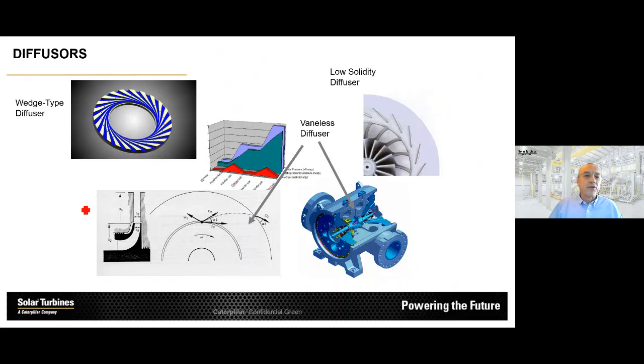After the impeller, and I had mentioned that in my slide, comes the diffuser. And we will talk about the function of that diffuser a bit more. The idea is that in the diffuser, we convert flow velocity into more pressure. An elegant way is to simply have, like in this picture, two parallel walls. And we get the diffusion, or the pressure increase, essentially because the through flow area entering the diffuser is smaller than the through flow area leaving the diffuser.